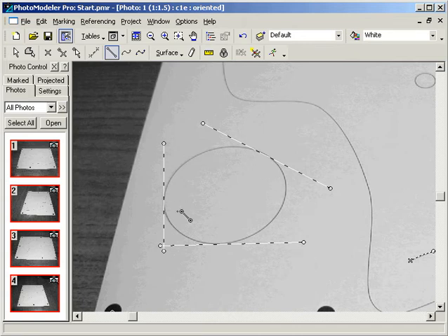The proper way to handle closed curves is to reference them across 3 or more photographs. You need 2 photographs that rotate around this horizontal tangent direction and 2 that rotate around this vertical tangent direction. Often with a closed curve, you would first try referencing across 2 photos and check the results. The third photo would be referenced to repair or improve weak sections of the curve. We delete the temporary edges we drew.